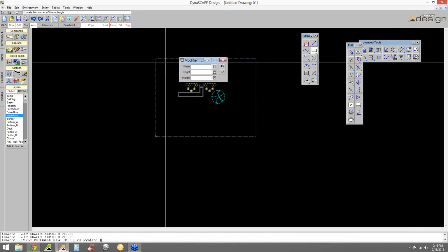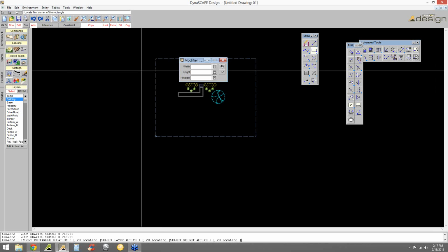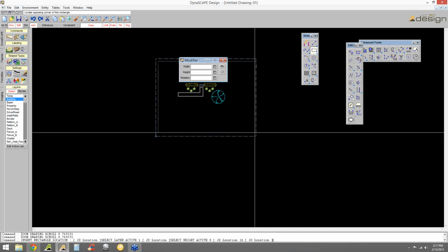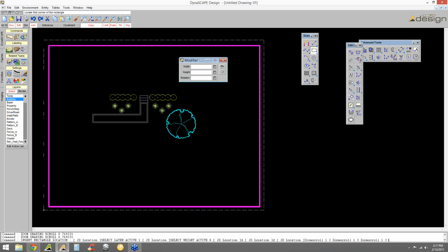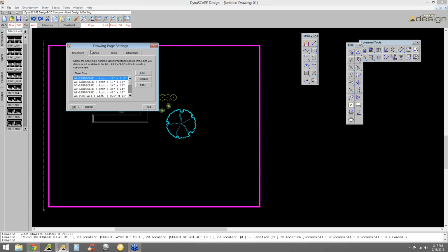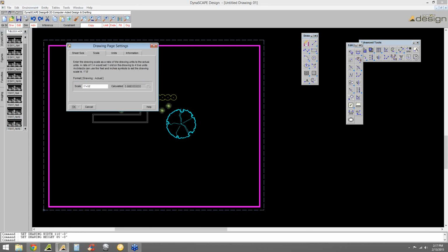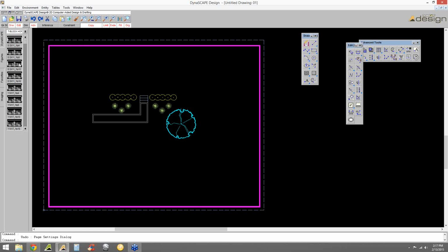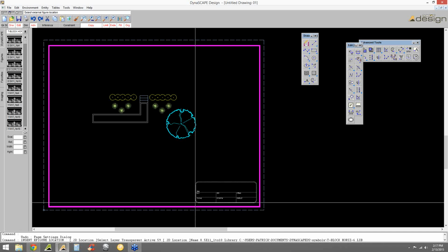So if we had a drawing, let's just put a real quick border on this, maybe like a building layer border. And let's go into our accessories or our figure libraries into title block accessories. Horizontal. There you go. The scale of the drawing is 1 inch equals 10. So let's go to 8.5 by 11, 1 inch equals 10, and let's just put this down in the corner.